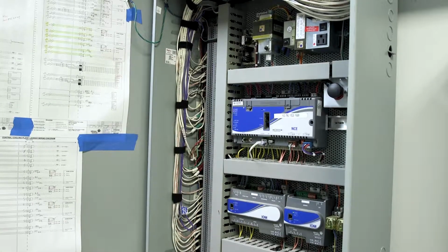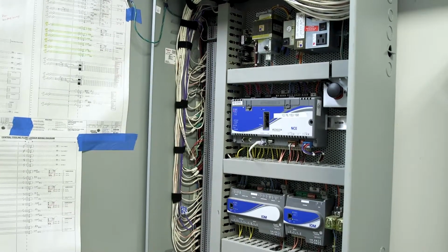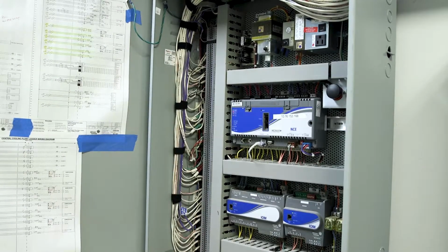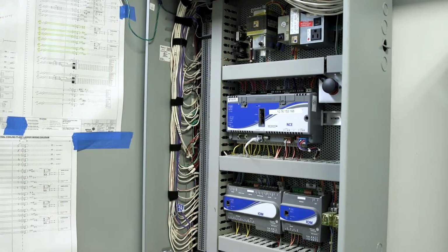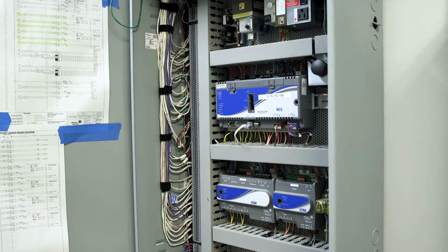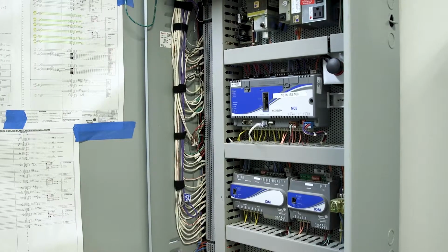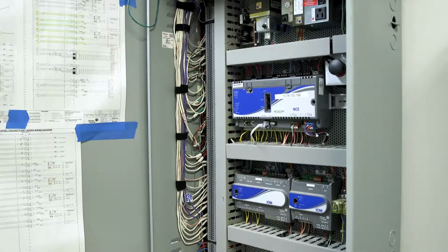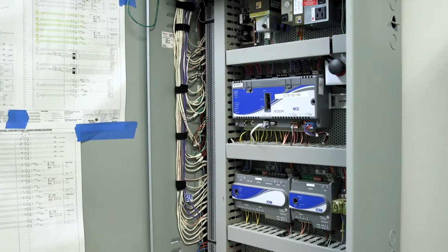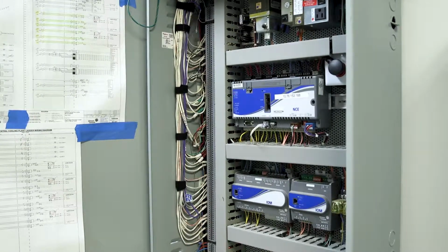No, because you have to define where your points go on the list. So if, say, you have a BO but there's no BOs available, you could use a CO. But if a CO is not available, then you're gonna have to add another controller, which would be an IOM. But you have to add those in the list actually in software in the CCT program. You can't do that from the head end. One of the things I was saying downstairs was you could add up to 7 IOMs to one controller. And the reason is you limit out the memory and the speed of the controller if you went past that. You bog the whole system down.